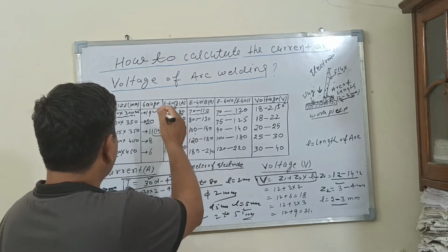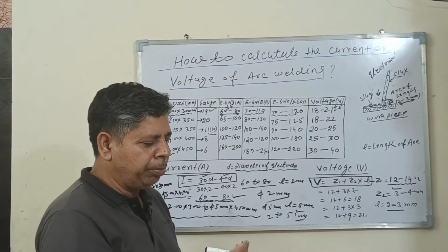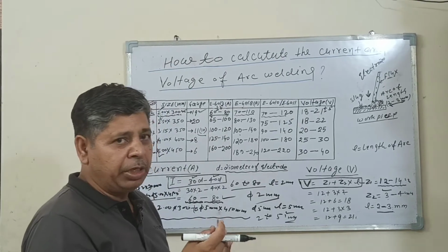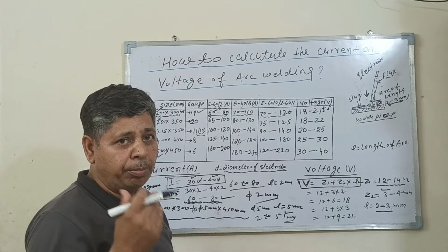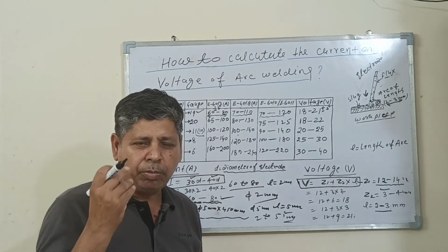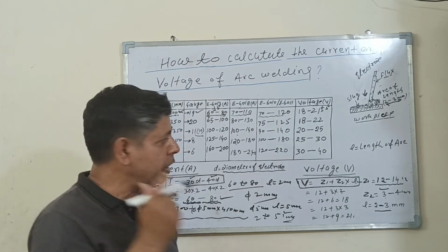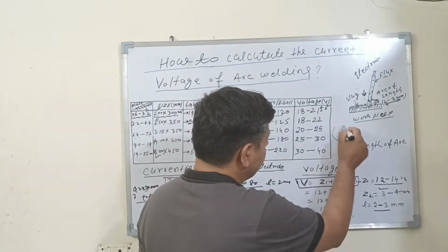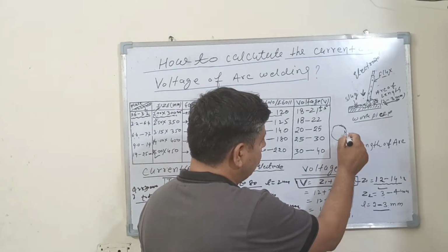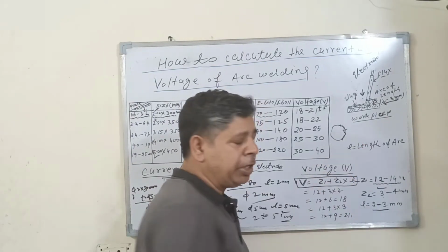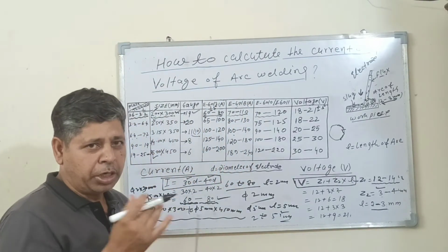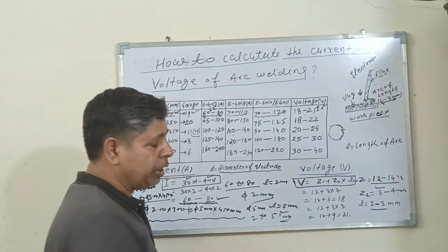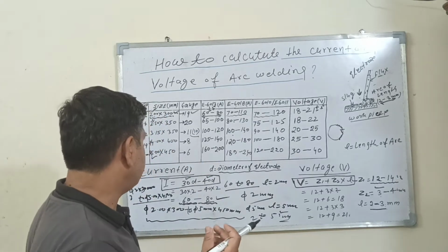The diameter of the electrode can be measured with the help of a wire gauge, vernier and micrometer. So what is the wire gauge? A wire gauge is just like a steel circular disc. A number of slots are cut on its periphery, and every slot has a standard value. The diameter of the electrode can be measured by the wire gauge, vernier and calipers.